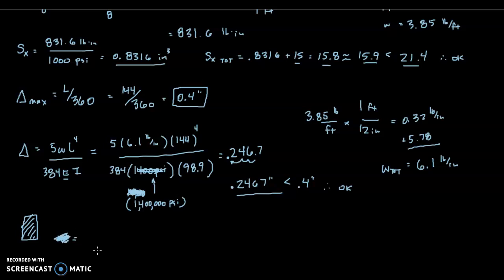Our formula is actually not set up to calculate shear strength, but rather the required shear area. The area required is 3/2 or 1.5 times the shear force that the beam is subjected to, divided by the allowable shear stress.